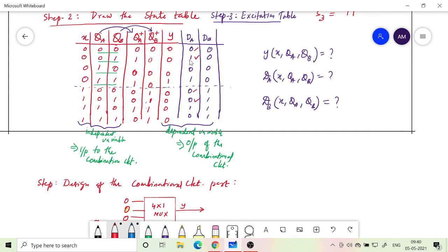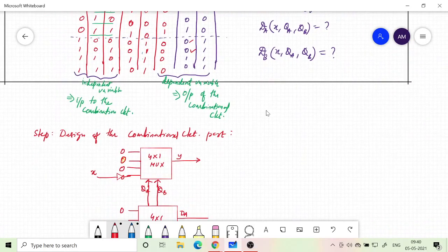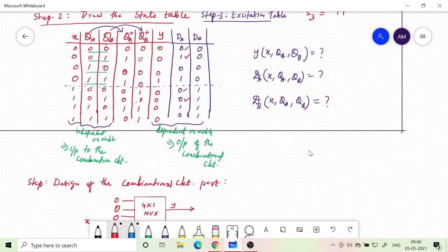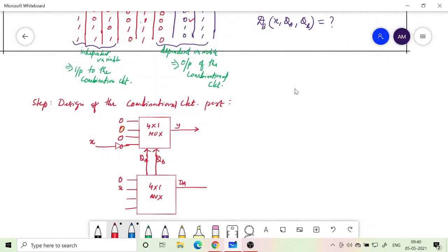So when X equals 0 it is 1, when X equals 1 it is 0, so it's going to be the complement. So this is going to be X bar again. The next one is 0 1. So 0 1 means it's X, so it's going to be X.